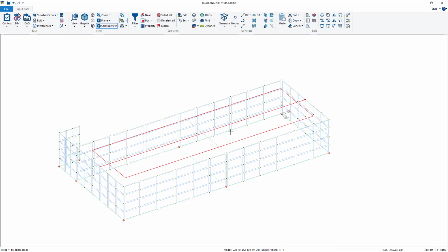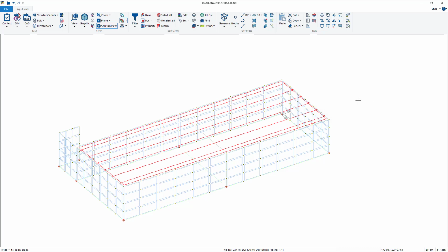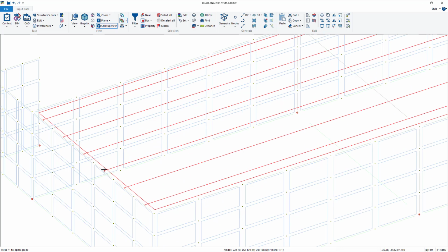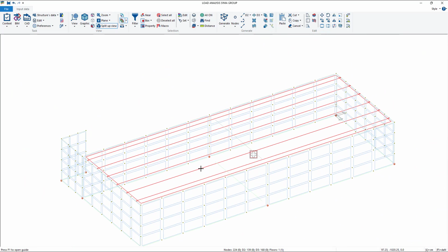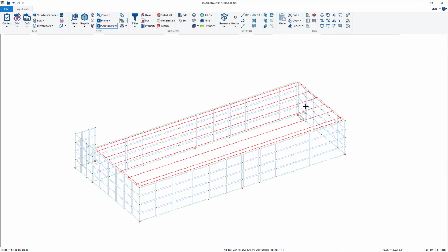With the floor selected, go right click, link element, modify topology for number one floors. It means that the software modified the topology for this selected floor. We go OK, and we see that now we have several lines, in particular one for each couple of nodes. This means that now our floor is well connected to the rest of the structure. Okay, now we can go.